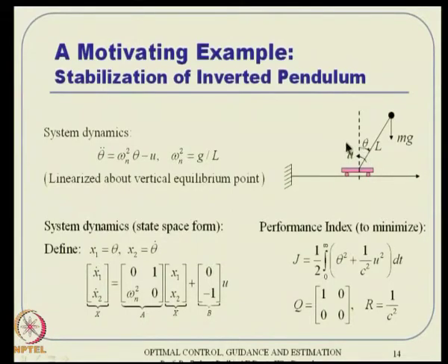But if you minimize theta dot on the way, then your response will be sluggish, your response will not be fast. So, if somebody is a little bit clever, they can initially operate with this cost function, and once it is in a very small narrow boundary, then you can switch over to the other cost function and apply the other controller. That is a possibility.